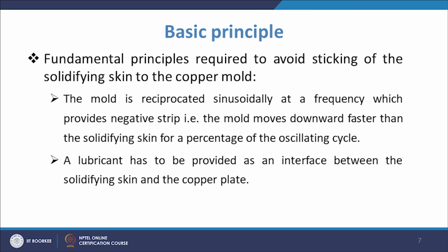Another thing we do is apply a lubricant at the interface between the solidifying skin and the copper mold. If a lubricating agent is applied, the skin will not have the tendency to get stuck or be pasted to the mold, so it will go down.